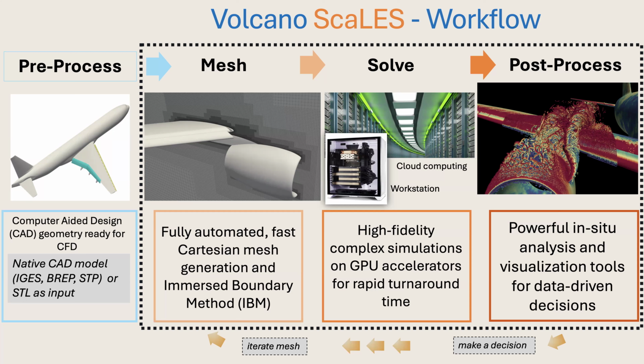So the idea is do not start with a fine grid. Always start with the coarsest grid you can. And after the grid generation, you run this on the GPUs you have access to. It could be two RTX 4090 type, an excellent machine for debugging, or if you have HPC access, you can run it there.